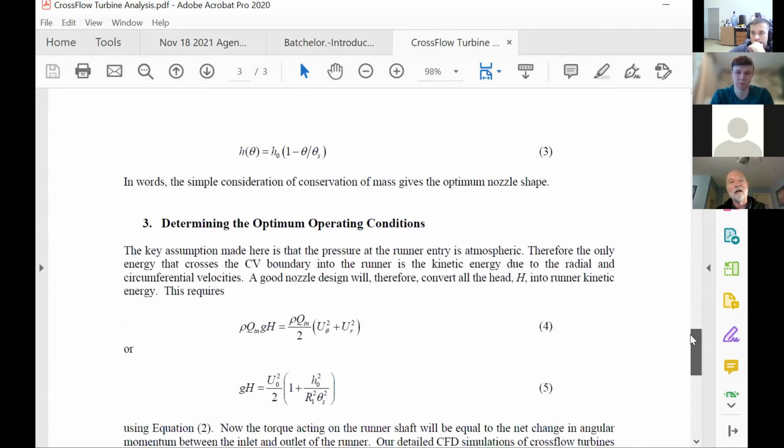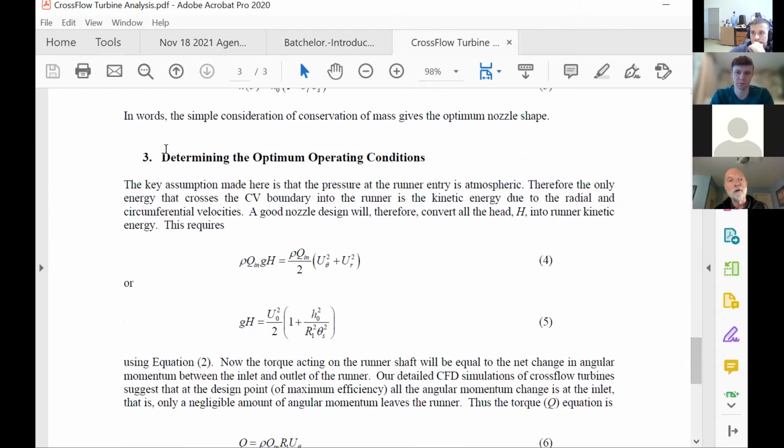Then if we go down to equation 4, we see the principle that I've just enunciated or just stated. This is the energy that's available from the water. H is the head, the available head. g is the acceleration due to gravity. Qm is the volume flow rate, and rho is the density. Sorry, that says Q in. Yeah, I think, yeah, that's why I put it there.